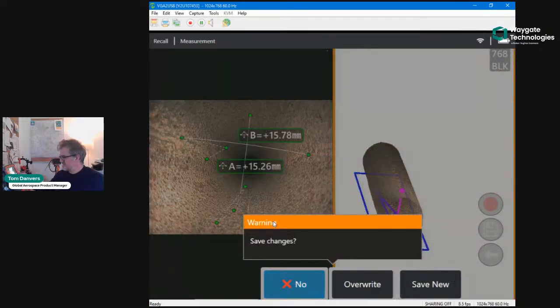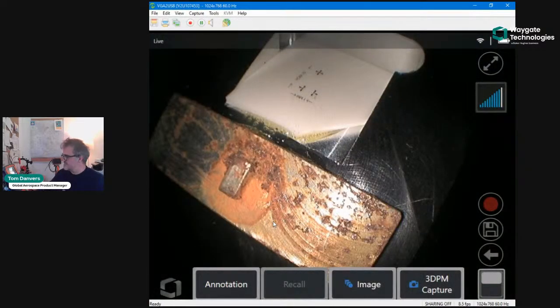So length measurements, there's lots that we can do. Just make use of all of the different features. Basic lengths are, should we say, dangerous to use if you're not checking the point cloud. It's very easy to generate diagonals and false measurements.